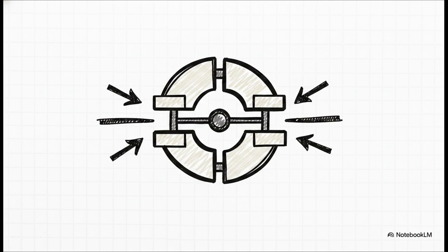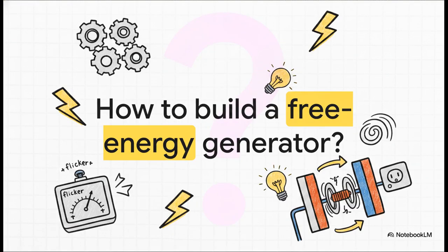To convert this into a DC generator, we just replace those two solid rings with a single split ring, very similar to what you'd find in a basic electric motor. Because of the split design, the side of the coil that happens to be moving upwards is always touching one specific brush, and the side moving downwards always touches the other. This little swap ensures that out in the external circuit, the current stops alternating entirely and flows in one steady, single direction.